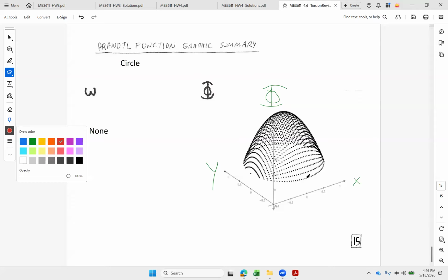So here I've got partial phi, partial y. It's going really steep up in y, doesn't have any slope in x. I could see it's flat across this direction. And partial phi, partial y is my tau in the x direction. So that goes right here. And then on the other end, it's sloping down. d phi dy is a big negative number, meaning the stress goes to the left, or against my tau in that x direction. And then over here, if I check this one, minus d phi dx is my other stress.